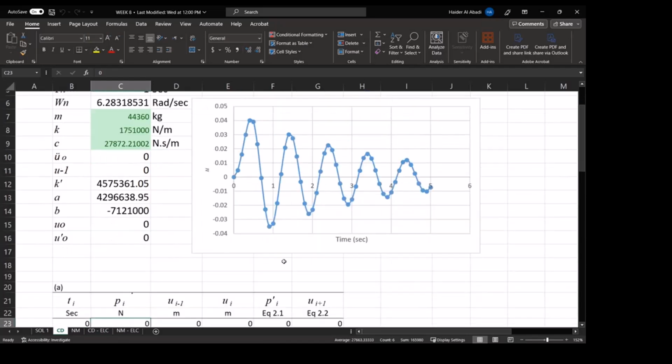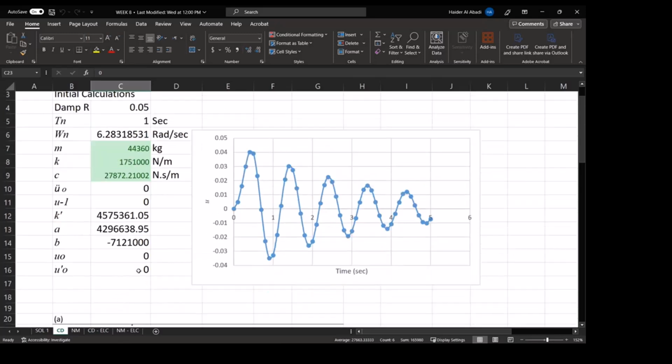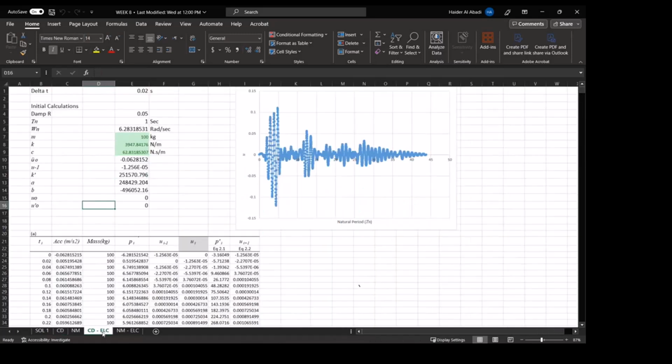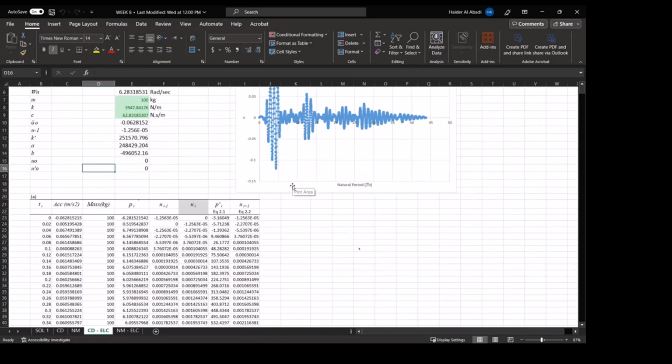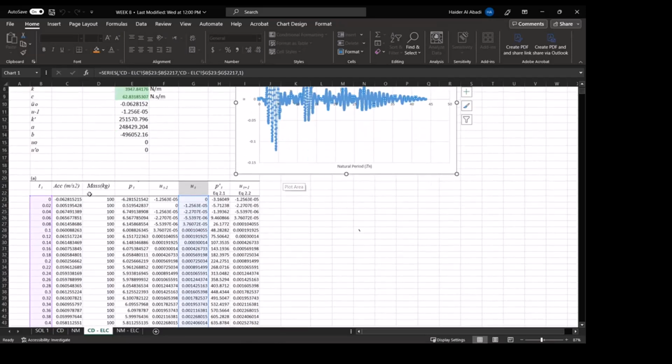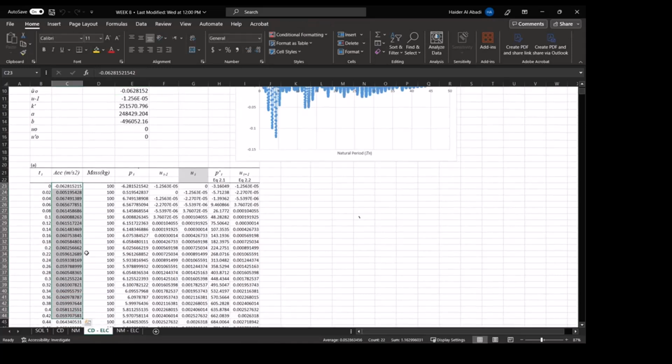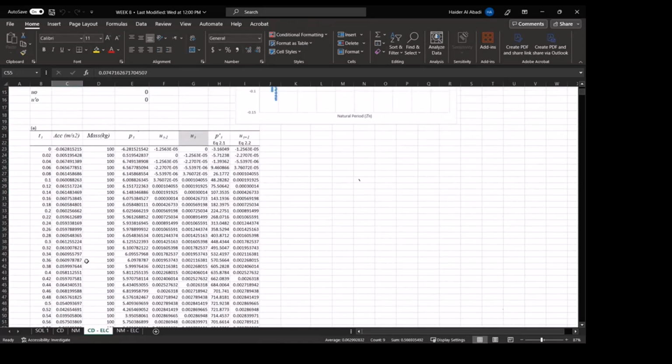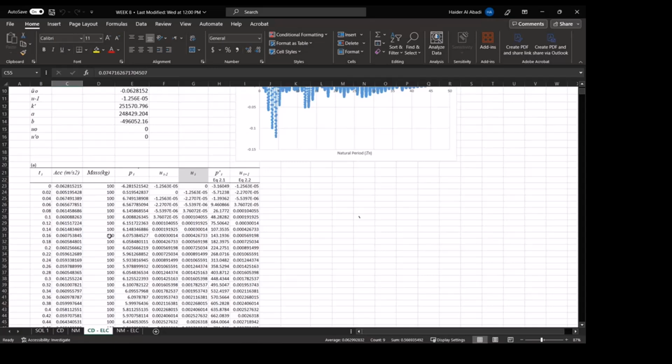Today, we will use that tool, or the calculator we developed, to consider a full ground motion, something like El Centro. And it's something like this. You're going to see here, this is basically the response of that same mass, but today it is not for a pulse, it is actually for a ground excitation, as you can see here.